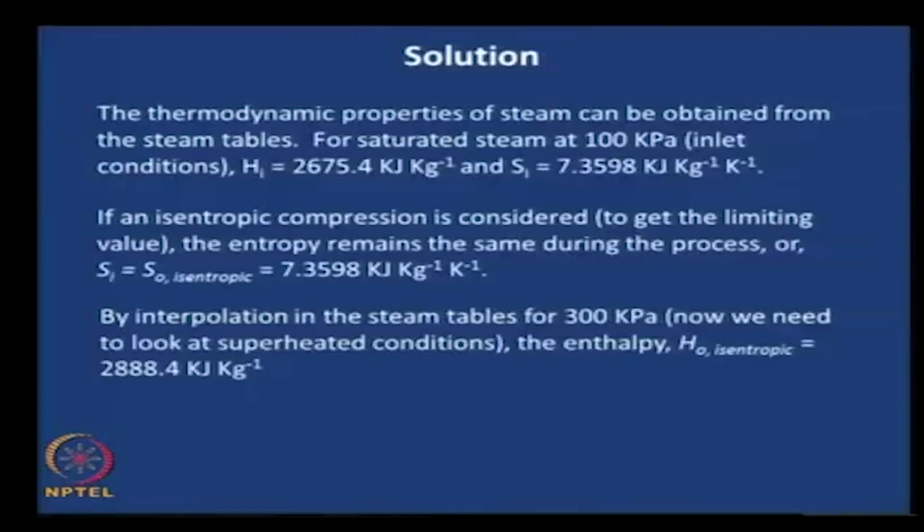Therefore for the difference that corresponds to 300 kilopascals from its previous value, what would be the change in enthalpy that needs to be added to the value that is before or below 300 kilopascals. That is the way we need to go about it. Please do that. If you have any difficulty you can always clarify later.